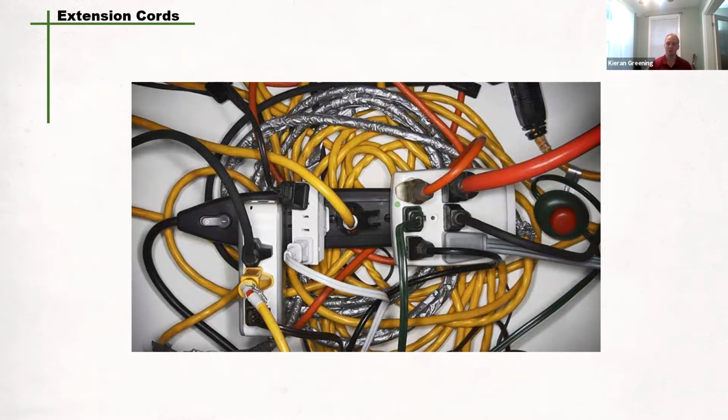For example, a block heater on a Ford F-150 requires a higher amperage than a smaller vehicle. So if you look at the amp rating, you might need a bigger cord. And if you don't have a bigger cord, it's going to pull more amps through a cord that can't handle it, creating heat, which in turn creates a fire hazard.